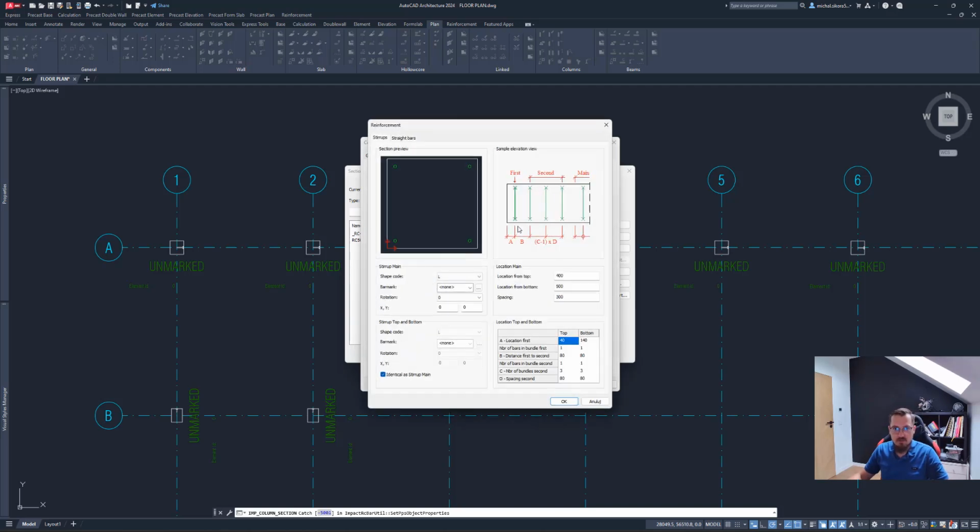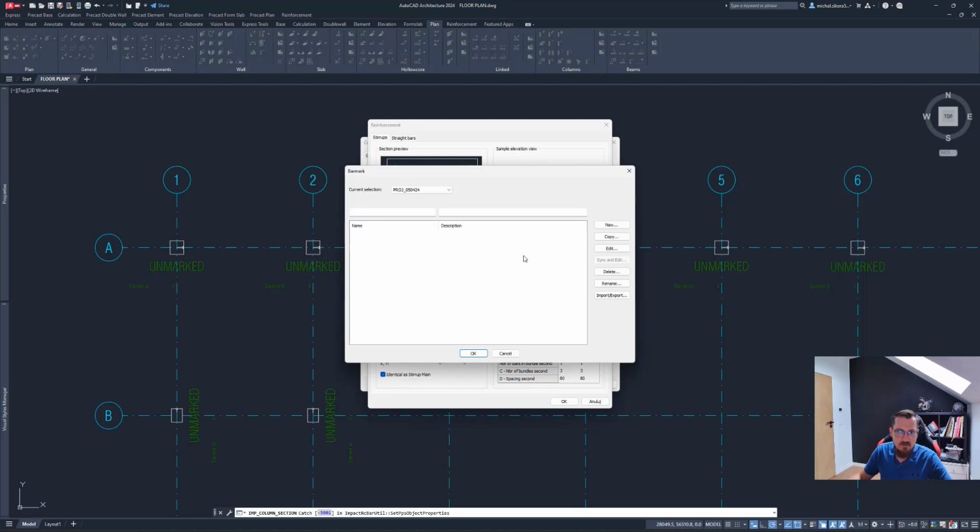Well, let's accept that. And another window immediately pops up for me to specify either the number of straight bars or the stirrups. The first one is stirrups. So I can utilize all the tools that I have here. First, the shape code. Is that like an L bar, or other L-shaped bar, or a different type of bar? Let's go maybe with a 51. Bar mark none. We can have a new bar mark 51.